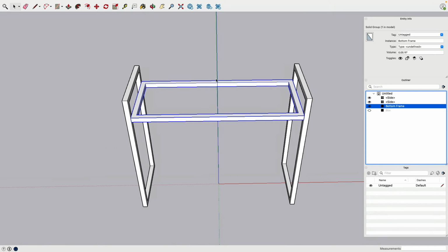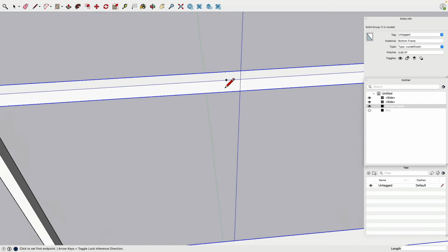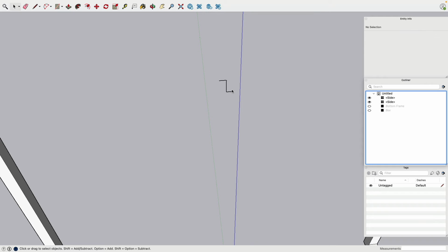Yeah, and then how do we put something in that's perfectly there at the center? That's also where SketchUp has a lot of very useful tools, because we can snap to the left and right point on an edge, and somewhere it finds there's the midpoint. Okay, so from here I draw a line down. Very good. I draw a line over by 0.5, and then from here a line over 0.5. Okay.